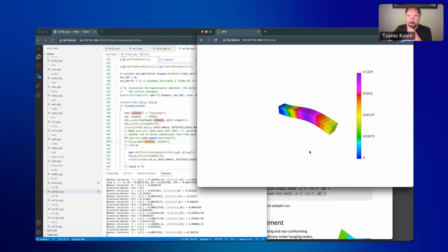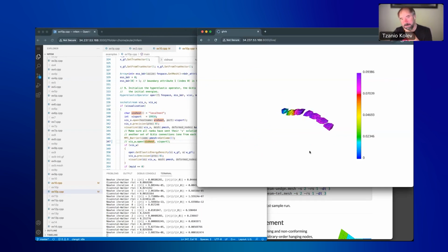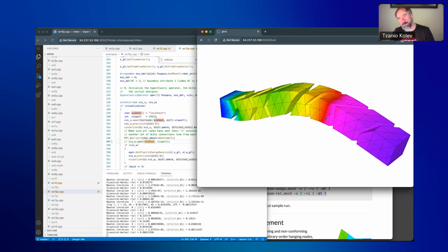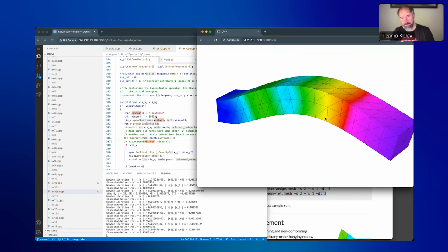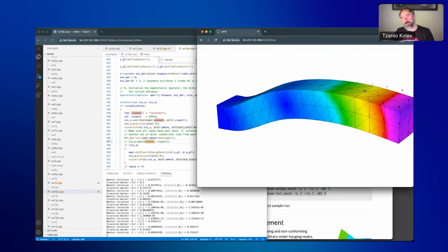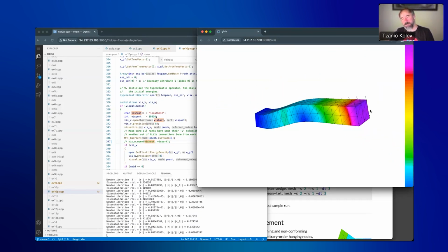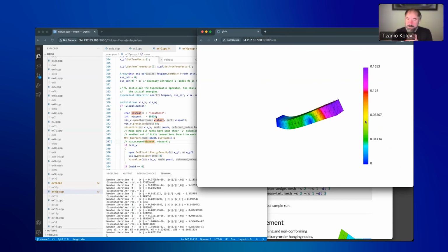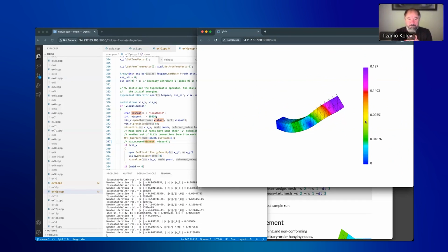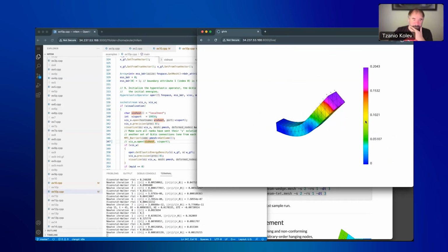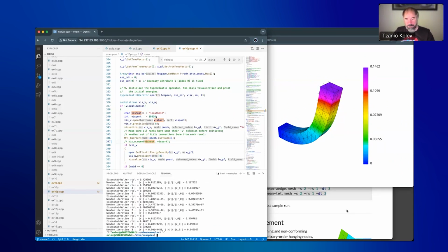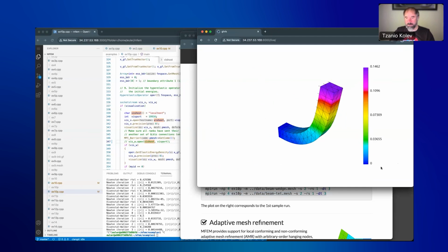And as you can see, this goes a bit faster. I run on 8 different ranks, so you can see I pull them apart with F11. You can see them being computed. There is all the displacements that are computed here with V. The other window that we disabled shows the elastic energy, so you can look at them at the same time. So I know somebody asked about nonlinear elasticity here in the chat. This is the right example for that, and it's one of the basic examples.